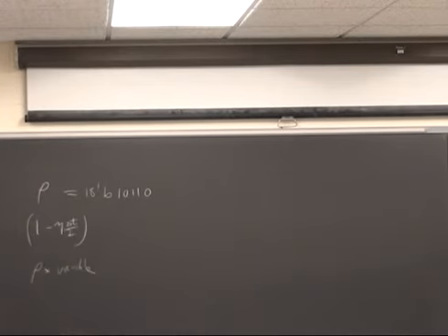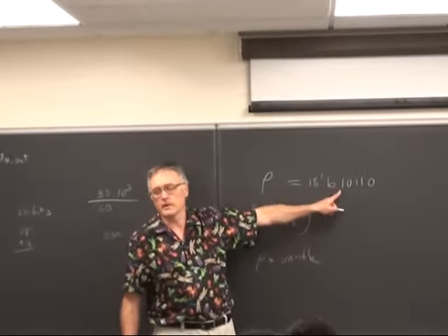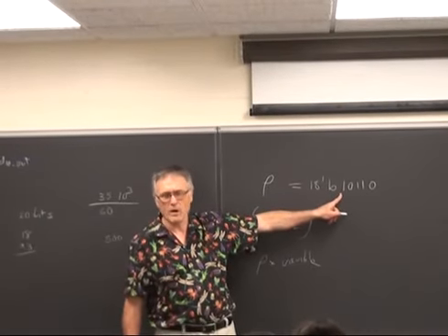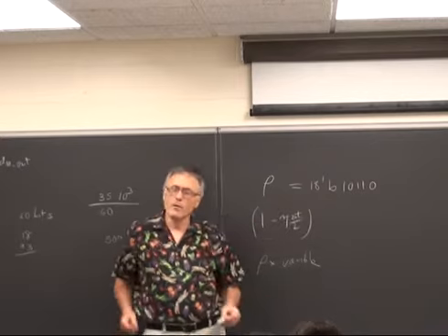That's an easy experiment to do, to find out whether you have to do the shift and add coding yourself or whether Quartus just does it for you. I don't know the answer. It may be that it depends. It may be that Quartus is smart enough to say, if there's only one bit high, surely we're just going to do a shift and add. If there's 2 bits, yeah, probably. But if there's 10 bits high, it's better to instantiate a multiplier. Don't know.